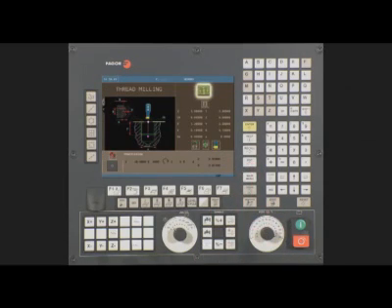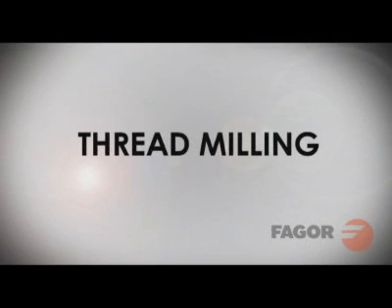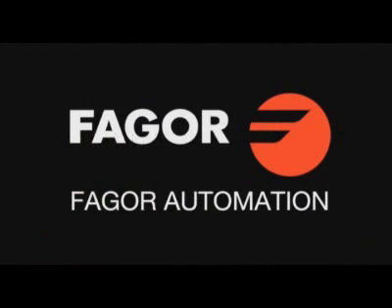You now see that there is a cycle start icon at the top of the screen. Turn down the feed rate to 0 and press Cycle Start button to begin executing the cycle. This concludes the thread milling example. Please feel free to rewind, pause, or review any part of this video to improve your knowledge of the 8055i MC CNC control.